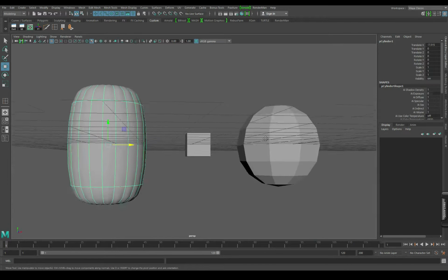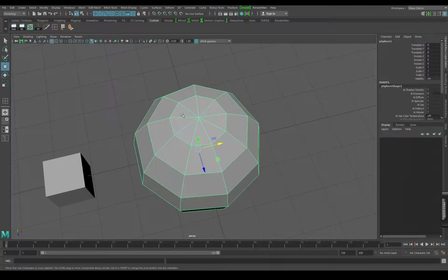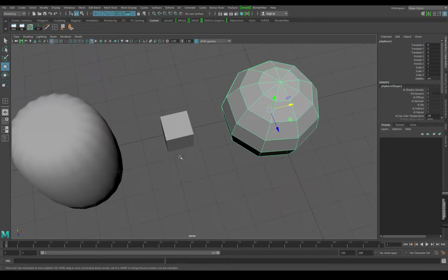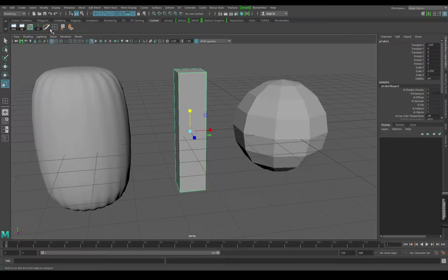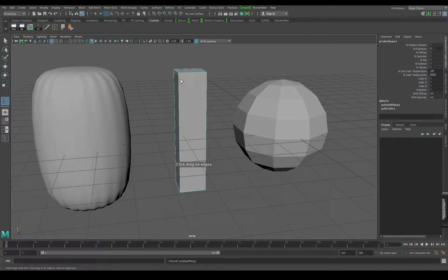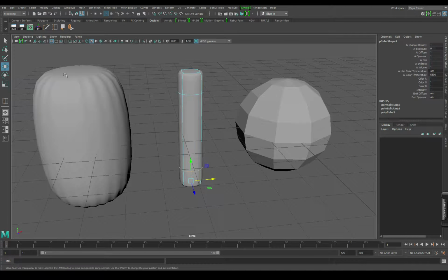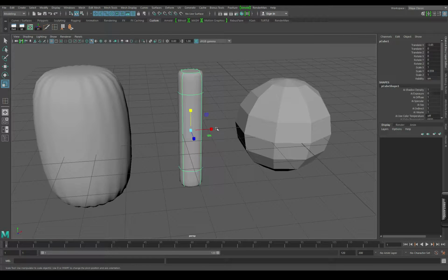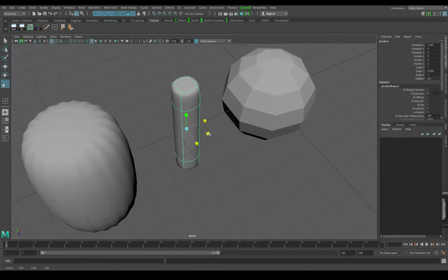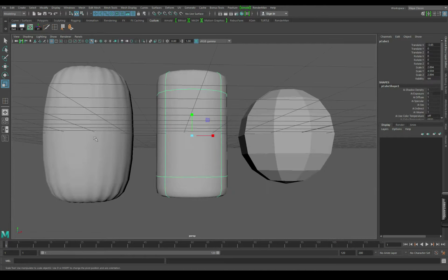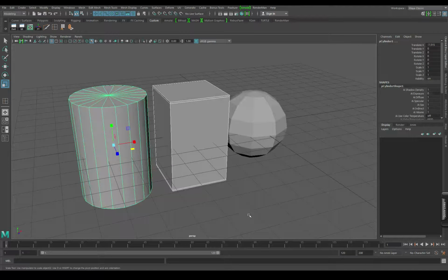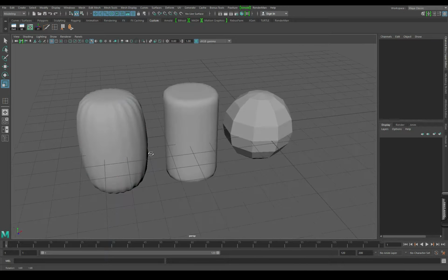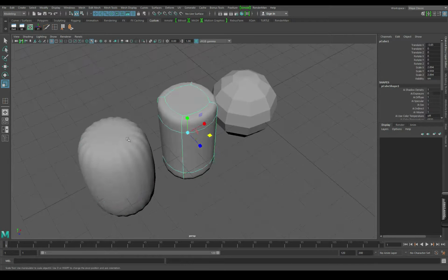that look. Now if I take this, okay, I've also got sides there, but I can create a cylinder from this just as easy. Boom. We'll get back to this, but this is an edge loop tool, and if I just cut it off over there and there, I get just a way cleaner version of that. So I want to do it on this side and this side, trying to get the same kind of sides. Let's hit 1. So they're pretty much the same, but if I smooth them, I get an extremely clean cylinder and I get a really horrible cylinder.